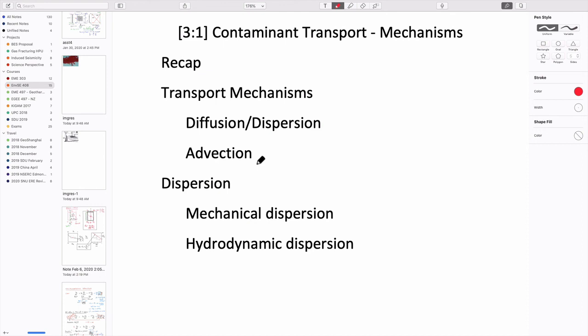Now we're going to assume that those basically stay in place, they don't move, but water moves in each of those cases. And if water moves, then it can dissolve the components and carry them downstream. And if we do that, then we need to look at a different set of transport mechanisms. One where diffusion occurs by the NAPL diffusing into the liquid, and also the liquid moves with that dissolved component and carries it downstream. So that's our next task on this.